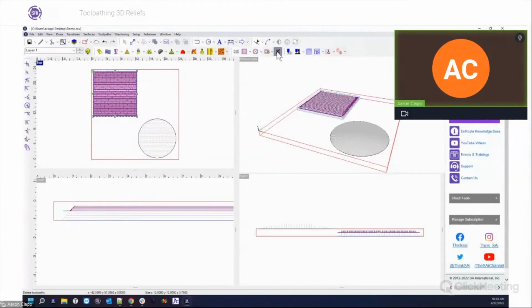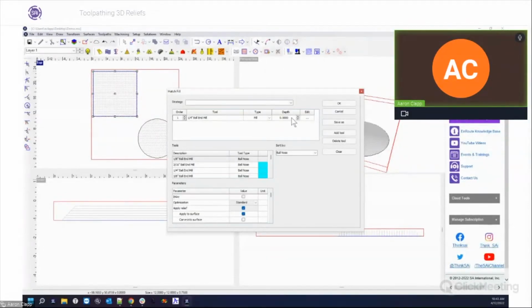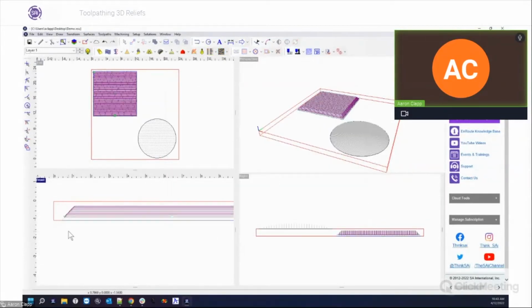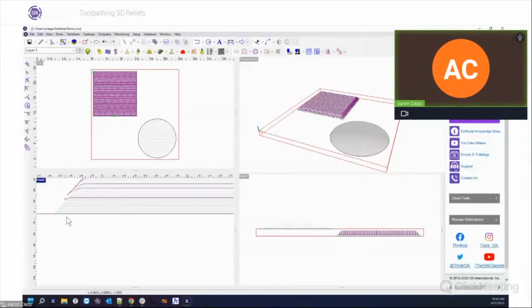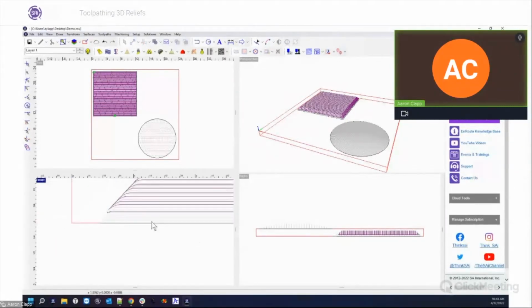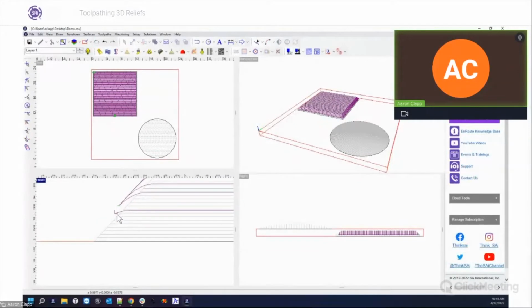So in my toolpath, instead of setting my depth to 0.75, which would be the depth of my relief, I need to add an additional 1/4 inch to cover this gap up here. So we're going to go 1 inch, apply, and that's going to cut. Now you will, for those of you who are savvy and have noticed, it still doesn't go all the way.